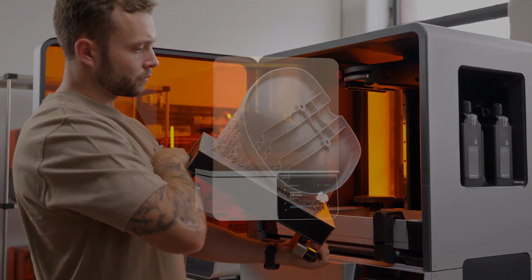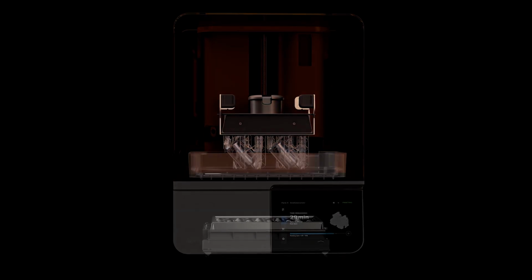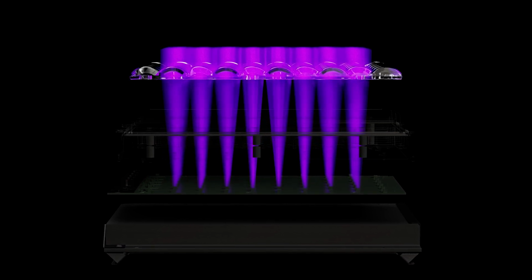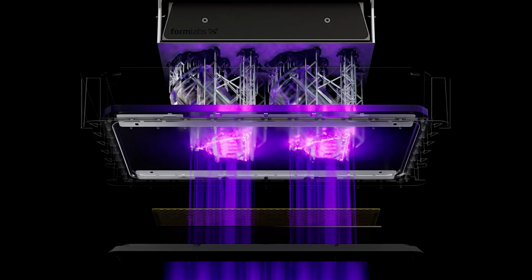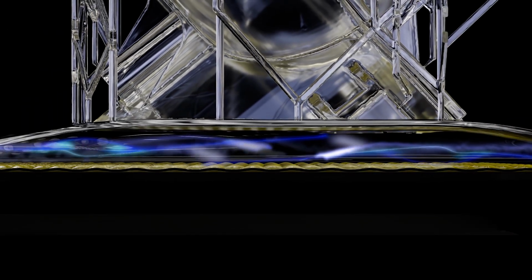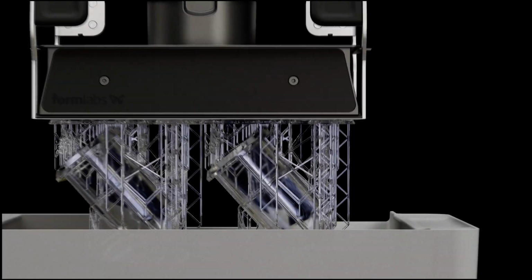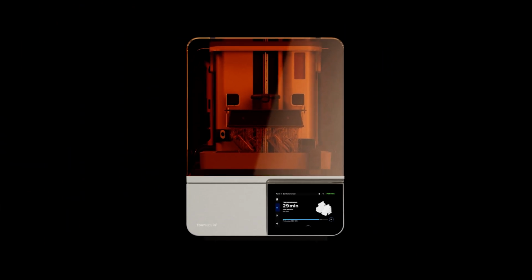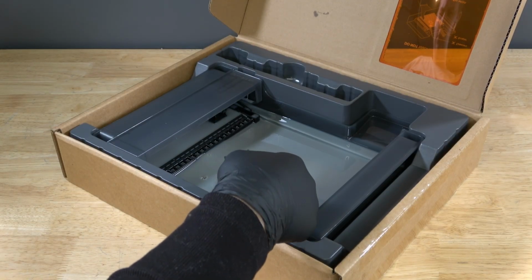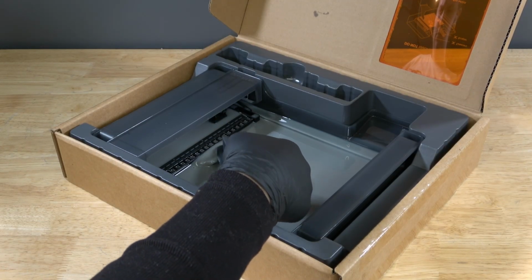As with a pinhole, an undeveloped feature or explosion starts with something blocking light from reaching the resin in a particular spot. For example, if a print partially fails and a chunk of cured resin sticks to the bottom of the resin tank, that piece blocks light from reaching the next layer of the print. The piece stuck to the tank expands with each additional cured layer and prevents other features from forming. This cascading growth creates the explosion-like effect.